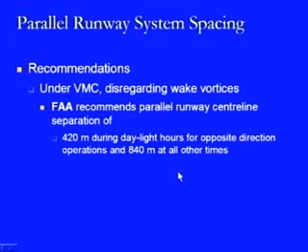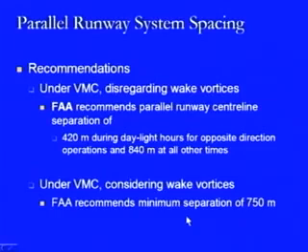In the case of VMC, the FAA recommendations are that the center line separation should be 420 meters during daylight hours for opposite direction operations and 840 meters at all other times. Under VMC, considering the wake vortices, the FAA recommends that the minimum separation should be 750 meters.